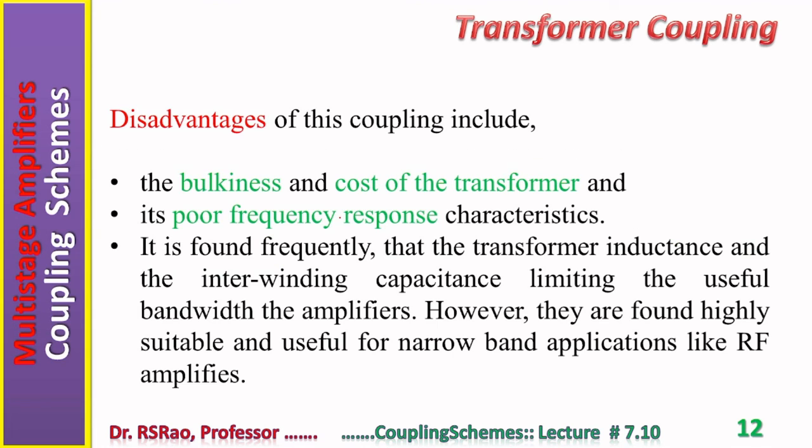Transformer coupling is also associated with disadvantages. What are they? Bulkiness. Space required is more for a transformer than a capacitor. So it is bulky. A transformer is expensive when compared to a capacitor. Poor frequency response characteristic is also a disadvantage.